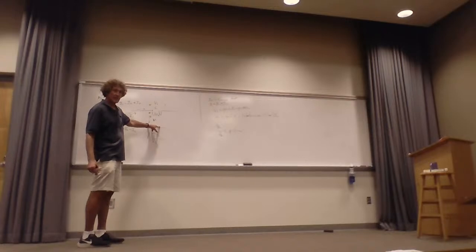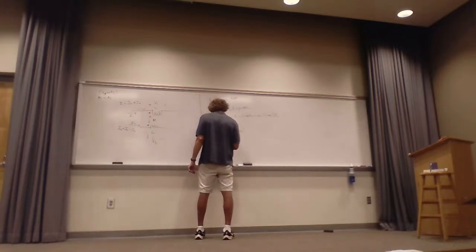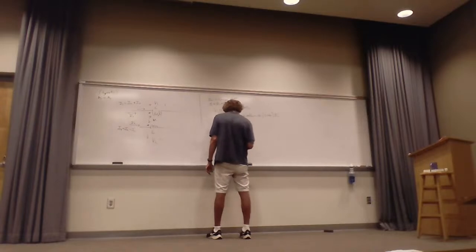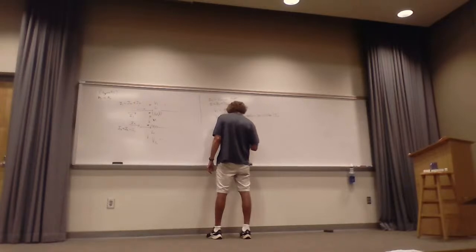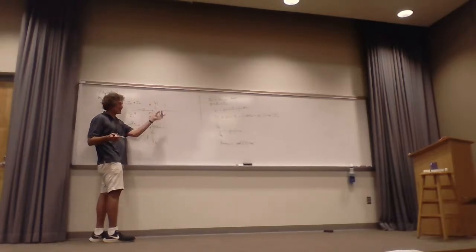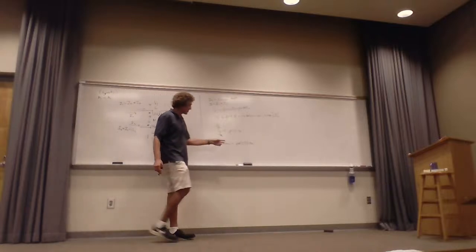Do y'all follow me? So I could say the total impedance of this circuit, which is just a common mode choke, I can call it Z common, would be j omega times 2 times L plus M. And that would be the effect of this and this. So you could stick in just one impedance of that value in series with that, and that would basically be the effects on common mode. Y'all follow me? Now remember, these two are going to be close together.